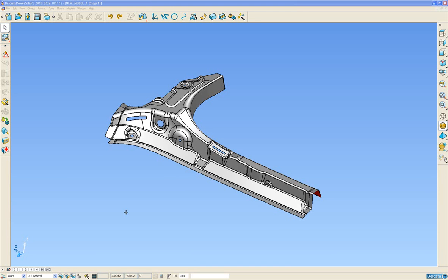In this demonstration, we're going to be focusing on the first stage of any modelling for manufacture demonstration, and this typically involves the alignment of the part to remove any undercut regions and checking the integrity of the data. So we're going to be looking for such things as duplicate surfaces, badly trimmed surfaces, overlapping surfaces and gaps between surfaces. And then finally we're going to be adding additional surfaces to the part to aid in the manufacture of the component.